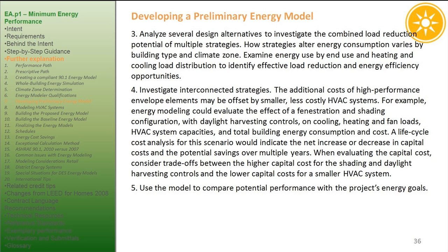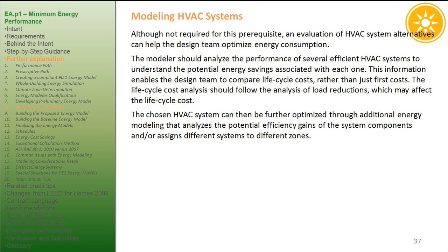5. Use the model to compare potential performance with the project's energy goals. Modeling HVAC systems. Although not required for this prerequisite, an evaluation of HVAC system alternatives can help the design team optimize energy consumption. The modeler should analyze the performance of several efficient HVAC systems to understand the potential energy savings associated with each one. This information enables the design team to compare lifecycle costs, rather than just first costs.